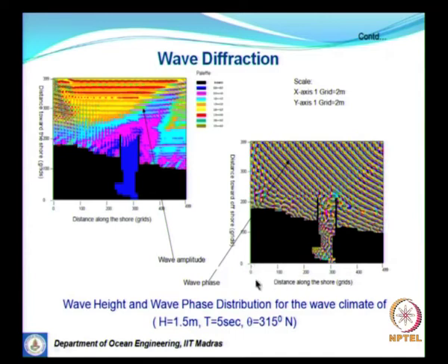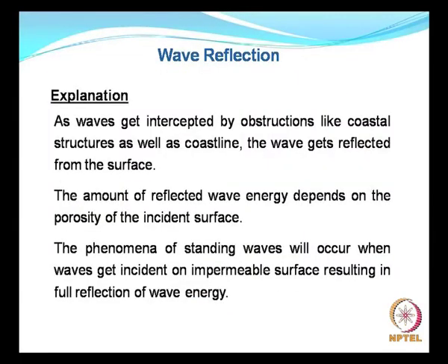So, here earlier we saw normal wave angle of incidence, now we have what are called phase contours, which show how the waves try to move. You look at this, you see that the waves are bending, and then once they enter an narrow area it becomes complicated because you have reflection from the side breakwaters, etc., and so you will have a different issue.